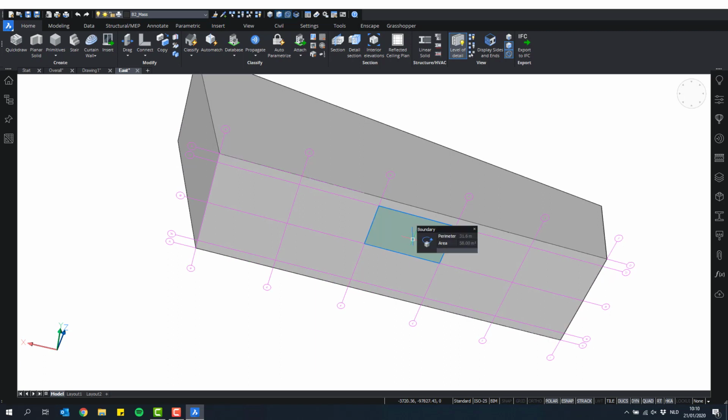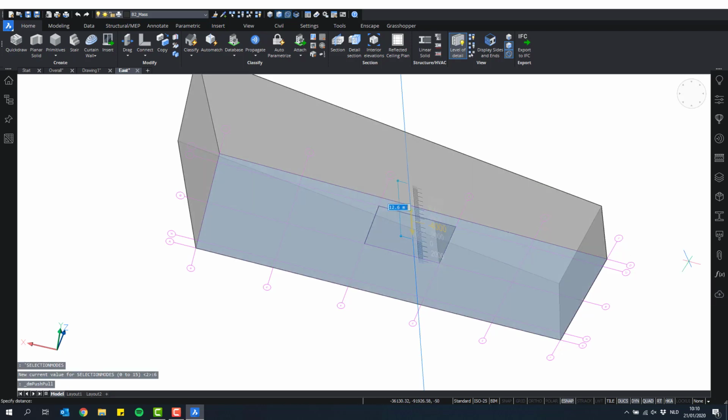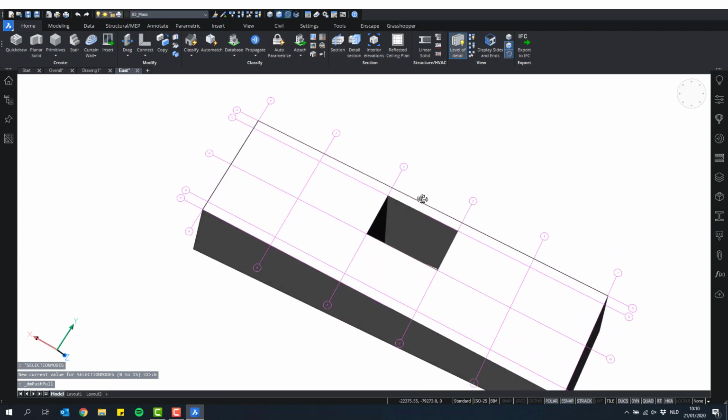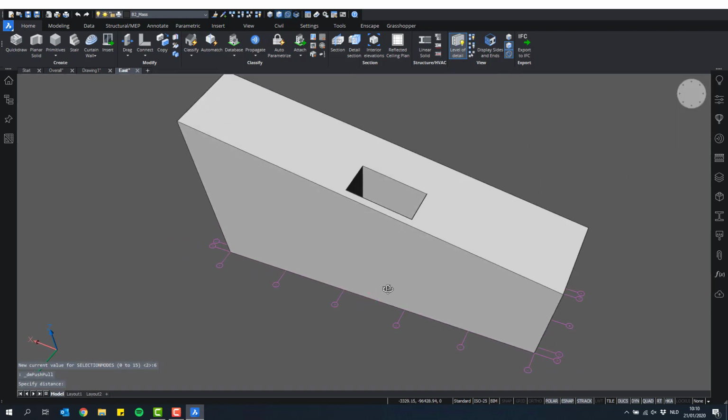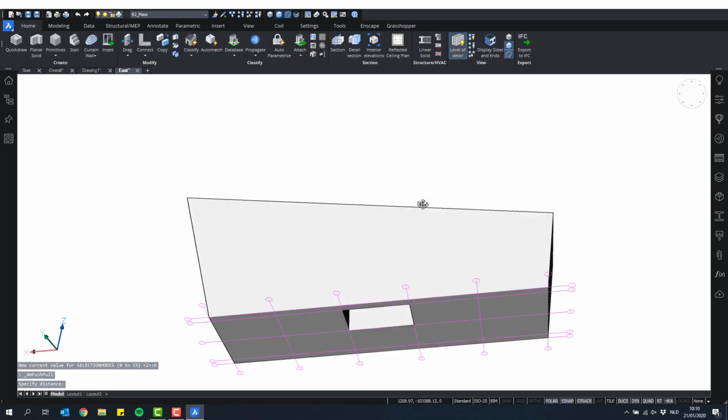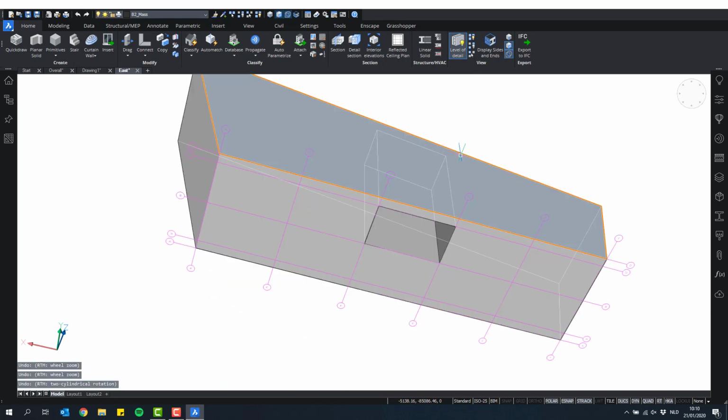So if I hover over this boundary and in the quad click, for instance, push-pull, you see I can push-pull a hole in this solid with this shape. So, like this. Actually, this is not what I want, so I will undo. I will Control Z.